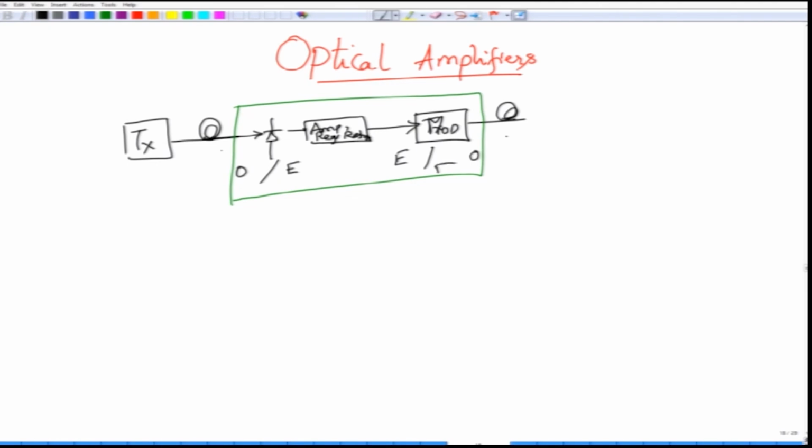So, of course, you would also require a laser diode at this point. So, you see that at every span you have to put a laser diode, you have to put a modulator, you have to put all these things. So, clearly giving us a problem in terms of cost, giving us a problem in terms of speed or the distance between the spans, right. So, the distance was also a major factor because you could not go far too long, because if you went far too long, then you see that the optical power would have dropped considerably over here.